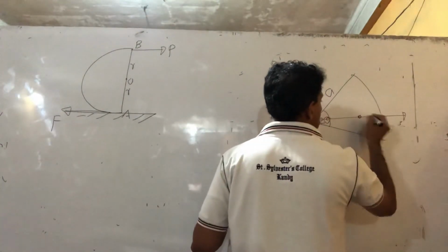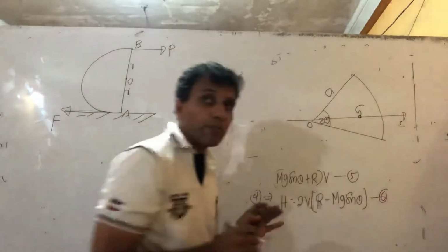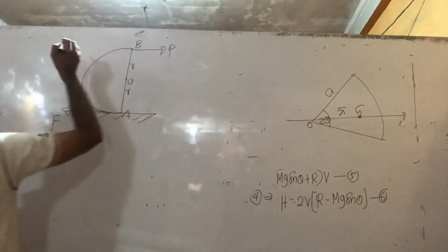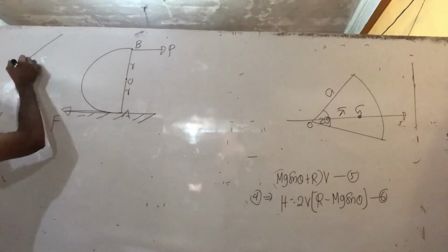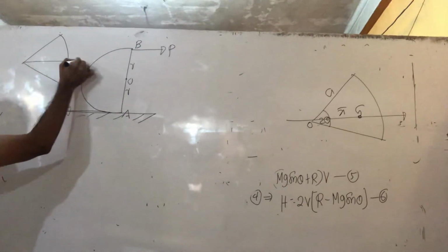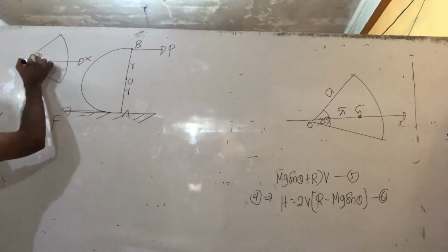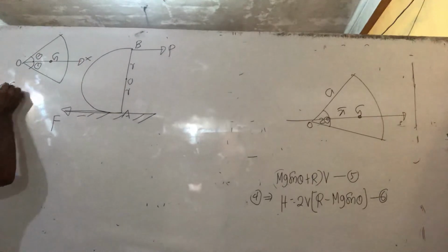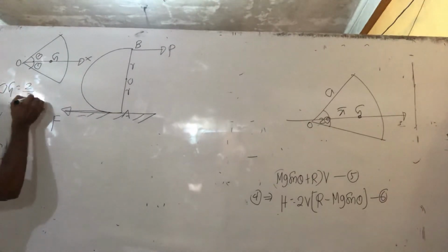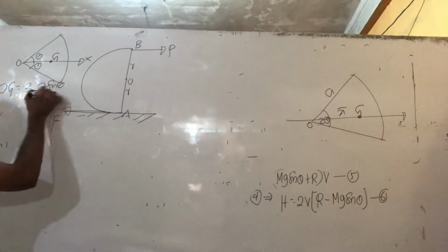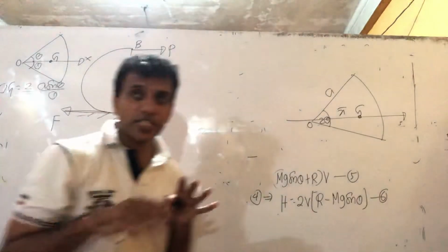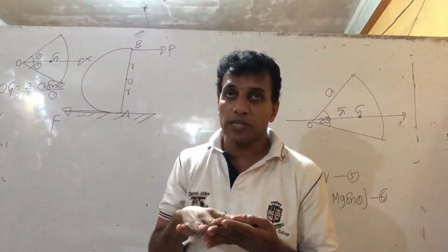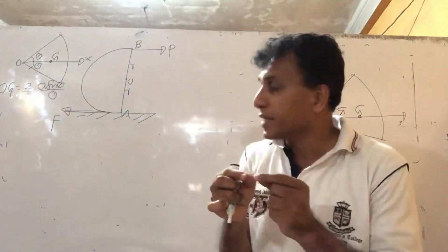Along this symmetric axis, the x bar, what do we call it? X bar equals, I show here, x bar. The center of gravity is at angle theta, here theta, and the center of gravity is G, here O. OG is 2/3 of what? A sine theta over theta is the answer for the CG, the center of gravity of a lamina portion of radius A which subtends 2 theta at the center, right?